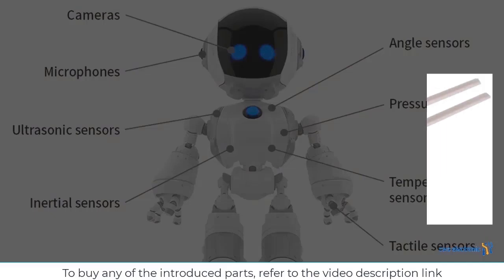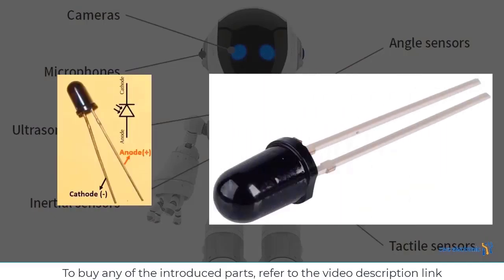The receiver is actually a type of transistor known as a phototransistor. You might be saying to yourself, well, it looks like an LED. While transistors usually have a different shape, this is also a transistor, and it's different from the transistors you've seen so far. In fact, this transistor is made to resemble a diode in that it has a transparent part so that infrared light can reach it. This phototransistor also has two terminals, which are like a collector and an emitter, but its base terminal is inside this transparent part, and instead of being excited by voltage, it is excited by infrared light.